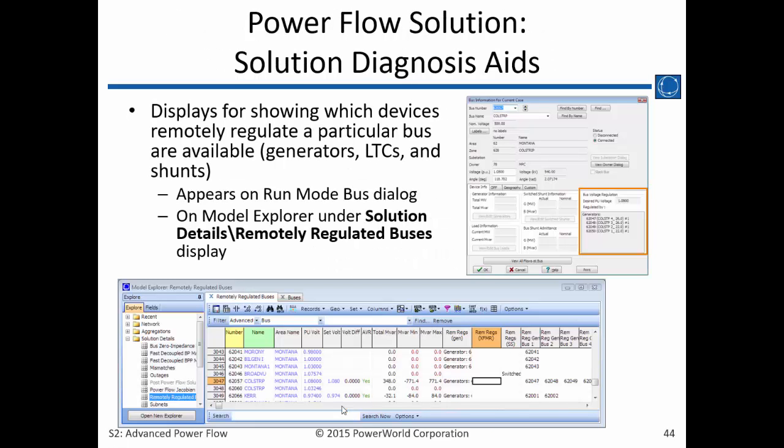There are some other solution diagnosis aids. Displays for showing which devices remotely regulate a particular bus are available. So generators, LTCs, and shunts. It appears on the run mode bus dialog.